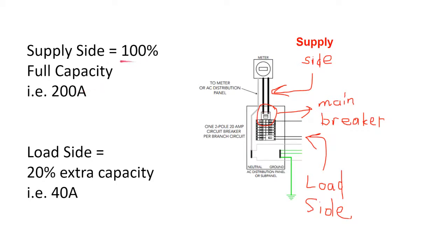Alternately, a load side connection can be selected. The load side amperage allowance is less than the supply side amperage allowance, and so is generally selected for systems which will power less than 100% of a building's energy, whether it be a small battery or a small solar array.